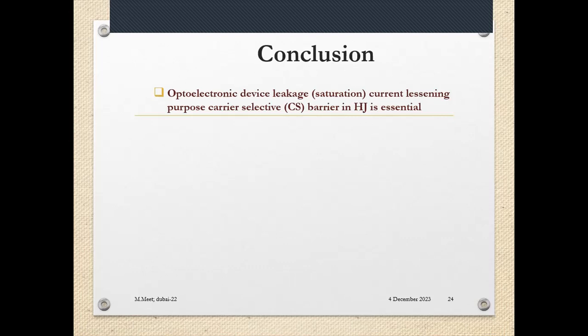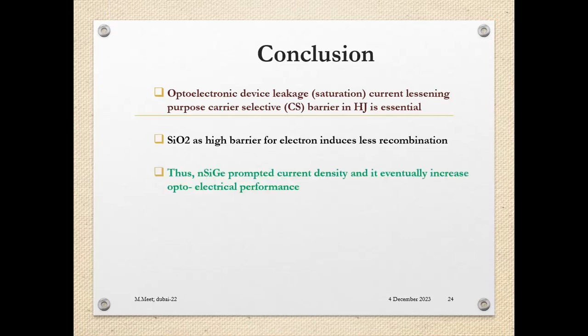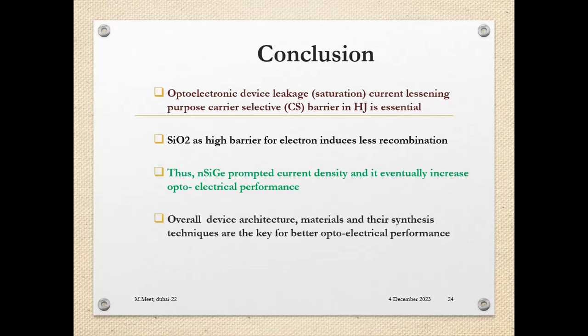Along with that, annealing conditions to decrystallize the materials and ensure a higher barrier for recombination avoidance, and that eventually makes a greater rectifying ratio, so ultimately the device should have a high signal to noise ratio, and that can eventually help design better transparent photo devices for the advancement of transparent flexible technologies.